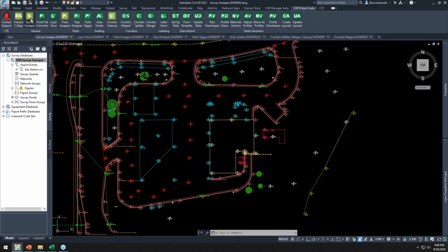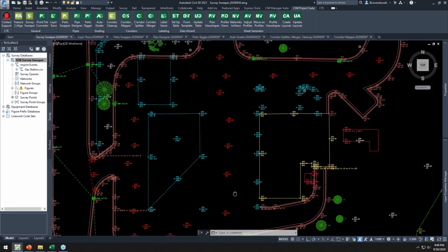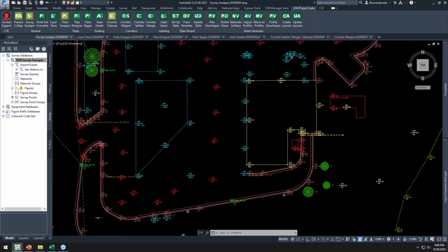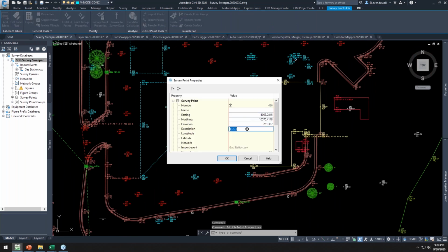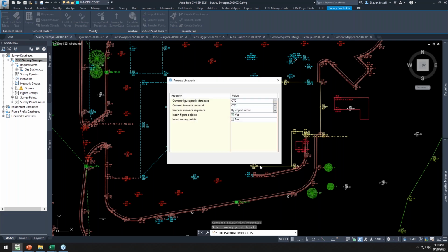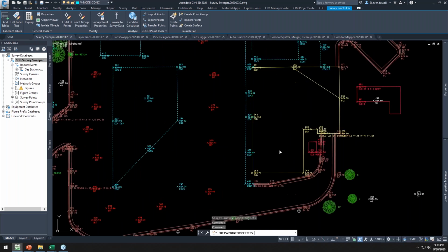So the second one, Survey Sweeper, is a free one as well. If you use survey databases, you know how tedious and kind of clumsy they can be. They're great in that they generate automatic line work for you from your topo surveys. But what about when you do things like this? What's real handy is to be able to fix coding mistakes in your survey codes. For example, I forgot a B code here. If I go ahead and update my line work so that it now draws that back of curb geometry, that's real handy and everything.